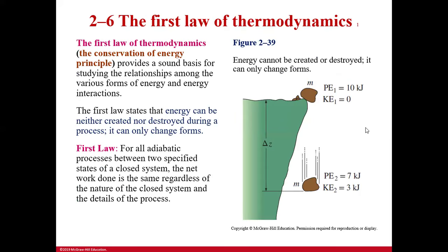First law of thermodynamics: the conservation of energy principle provides a sound basis for studying the relationship among various forms of energy and energy interactions. The first law states that energy can be neither created nor destroyed during a process. It can only change forms. First law for all adiabatic processes. Remember, adiabatic process means no heat transfer between two specified states of a closed system.